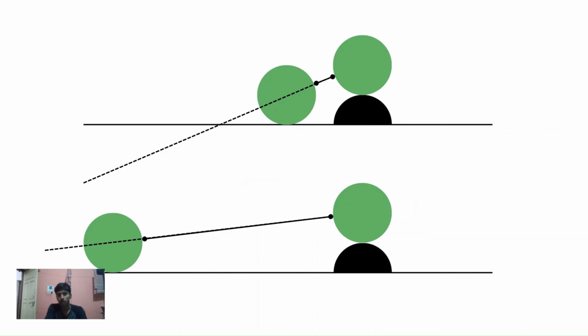Next, take this example. When you are going in a car with a longer wheelbase and a car with a shorter wheelbase on the road, and you face some obstruction like a speed breaker, a hump, or a pothole, what happens is that in a car with a longer wheelbase, the pitching motion created by the obstruction is lower as compared to that with shorter wheelbases.